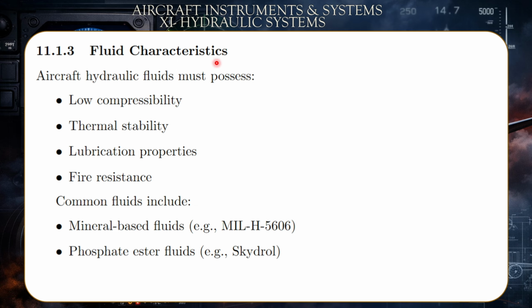Fluid characteristics. Aircraft hydraulic fluids must possess low compressibility, meaning they should not change in volume under pressure. Thermal stability, meaning the pressure should not change due to an alteration of temperature through hot or cold weather, for instance.